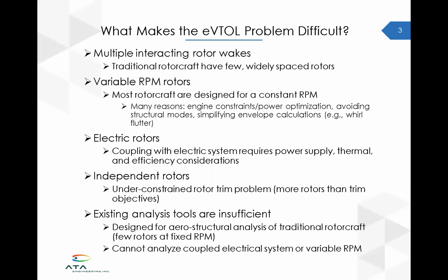These vehicles tend to have a lot more rotors than a traditional rotorcraft, which may have one in the case of a helicopter, sometimes two, and in a forward flight aircraft might have two or four, but these are generally widely spaced. In the case of eVTOL, they're much more closely spaced, and so the aerodynamics problem gets more complex because of that. The fact that these rotors are variable RPM is also a complicating factor.